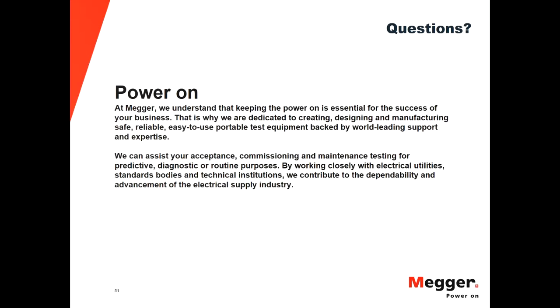All right, next question. Why has ANSI/NETA chosen to remove guidance on cell internal ohmic values for vented nickel-cadmium batteries in MTS 2019 Part 7.18.1.2? The 2015 standard contains specific guidance. So I don't know exactly the reason for this. One characteristic of nickel-cadmium batteries is that, different from the lead-acid batteries, the nickel-cadmium will not dissolve into the electrolyte as the lead-acid does in these types of batteries.